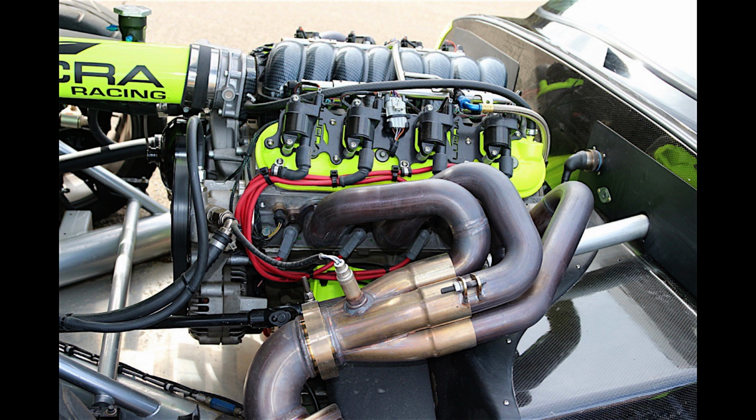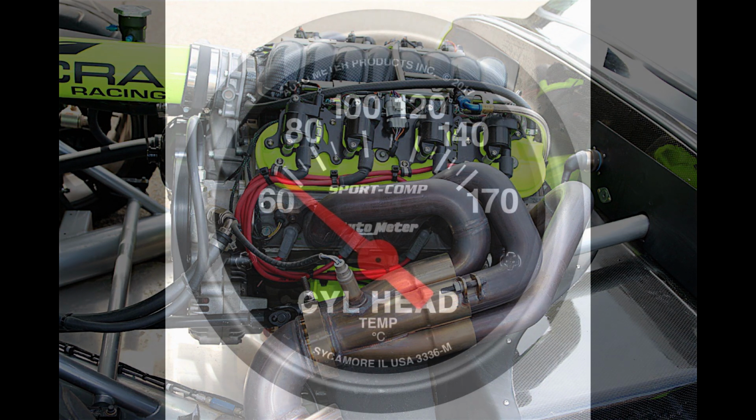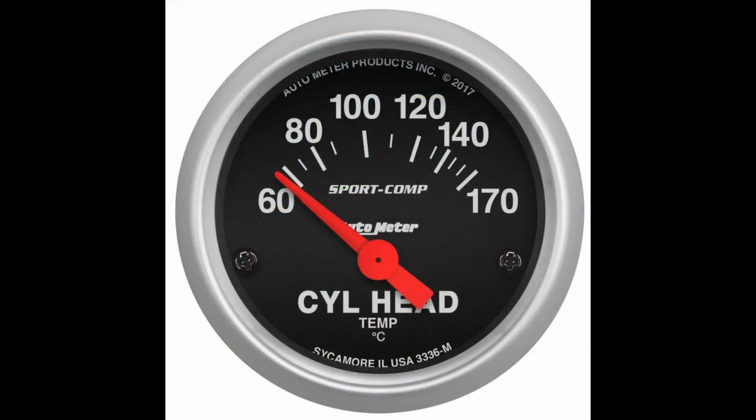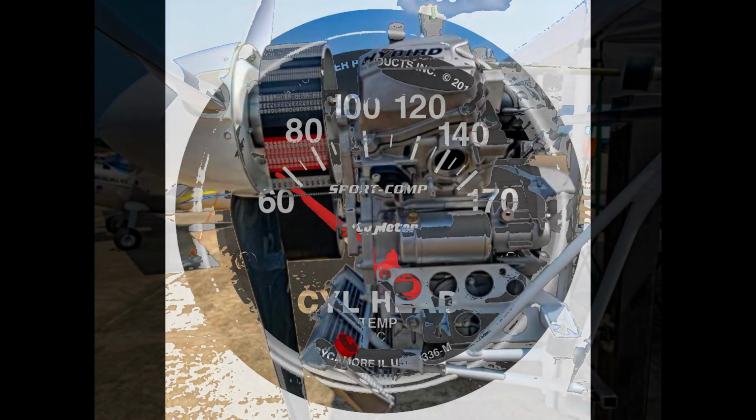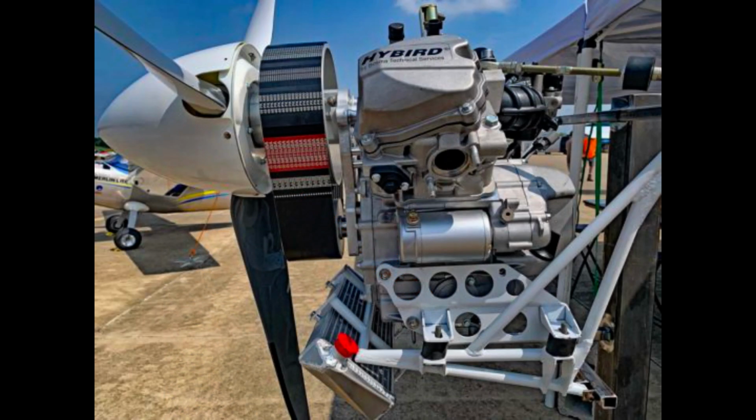Engine warming. Two-stroke engine warming. Two-stroke engines must be warmed because different metals expand at different rates as they are heated. When heating steel and aluminum, the aluminum parts expand faster than the steel parts. This becomes a problem in two different areas of many two-stroke engines. The first place is in the cylinders of the engine. The cylinders have steel walls that expand slowly, compared to aluminum pistons that expand quickly.